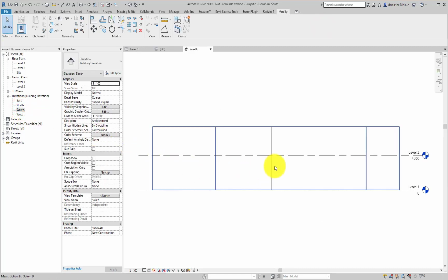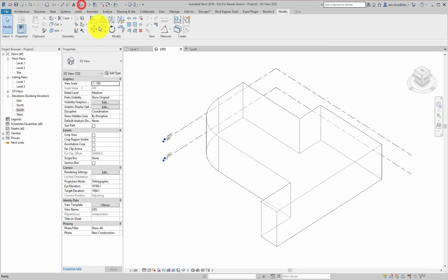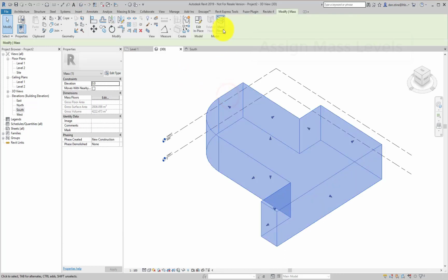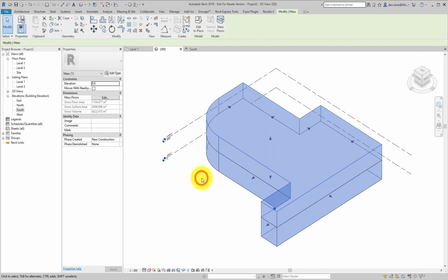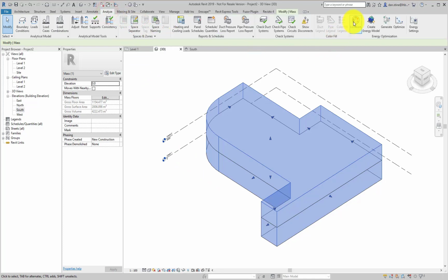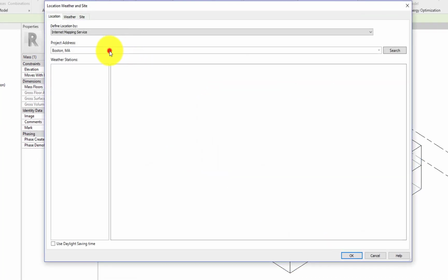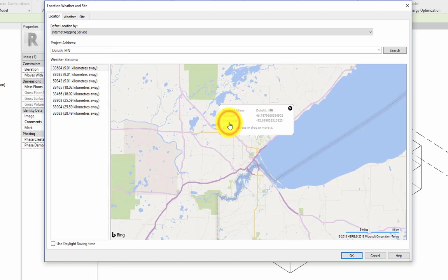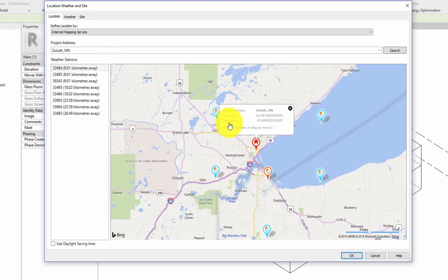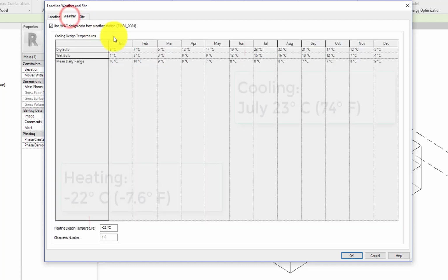We're going to go to an elevation and make sure our second floor level is at the correct elevation. And in this case, we're going to superimpose Level 1 and Level 2 as mass floors. So we select the mass. On the ribbon, we select the Mass Floors command. That gives us the opportunity to create those analytical floors. That gives us the correct square footage for the overall building, and it also helps the algorithm to figure out spaces within the building.